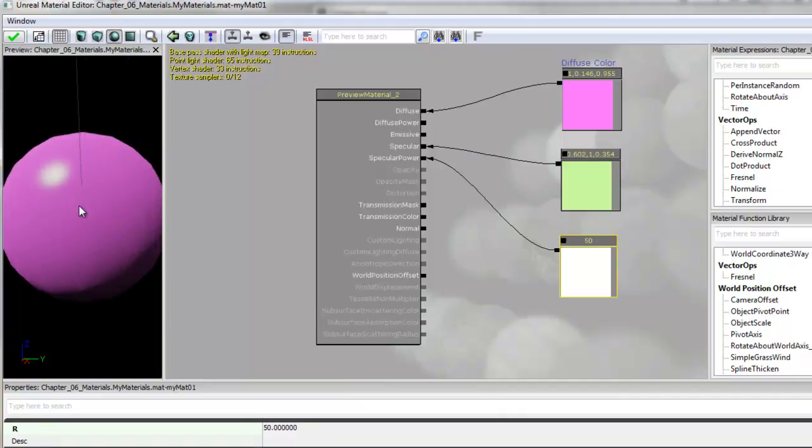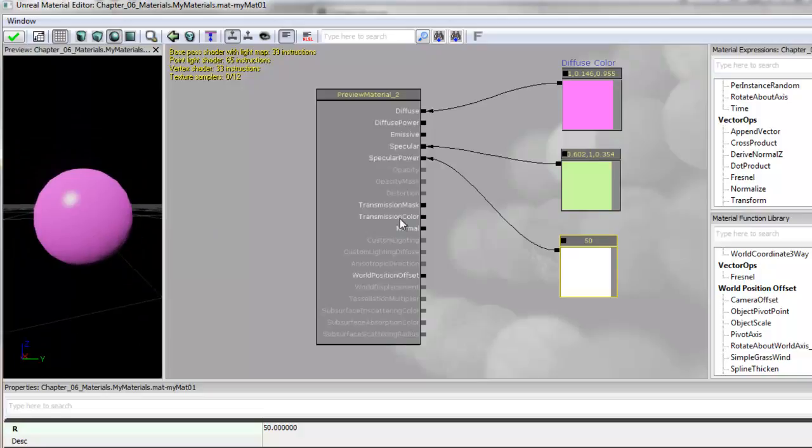Okay, so here's how it looks like. If you decrease this value to, for example, 0.1, you'd see that the specularity is larger. And 1 is a constant value that dictates how much your specularity is. So 500 is very, very high in specularity, so the light reflects back on a very small surface.